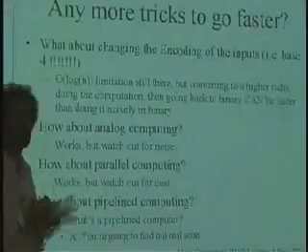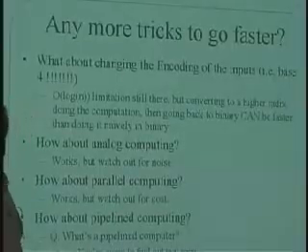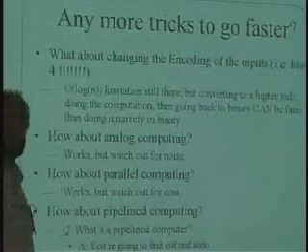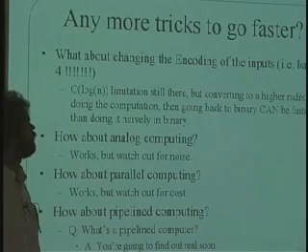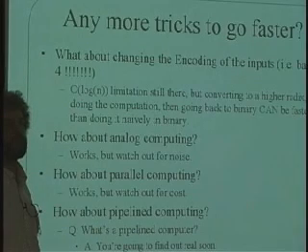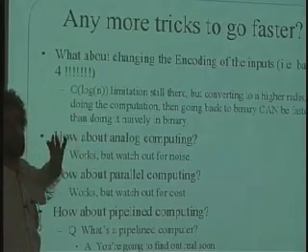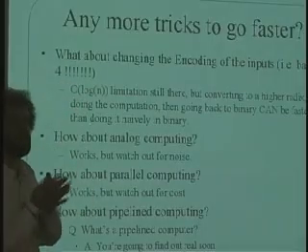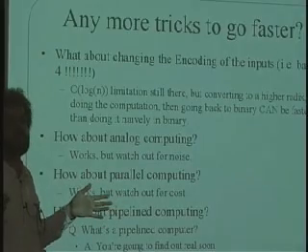We've been only doing things in base 2. Well, what if we changed it to base 4 and operated in base 4? It turns out that you can actually build a faster adder if you do things in base 4, or even base 10. Usually they don't go higher than 10, but this recoding to a different base is something that is commonly done in the high-performance adders you see in real high-end chips. You're still up against order log n if n is big, but the constant factor can go down. Recoding to more bits always means that the amount of hardware you dedicate to the add begins to grow very big, but the speed can go up.